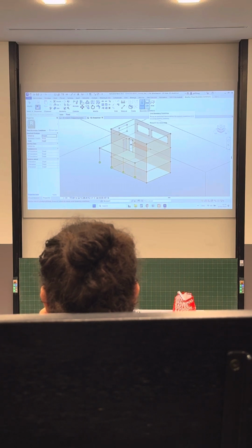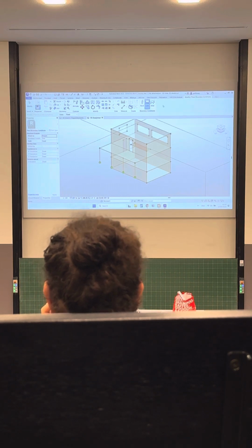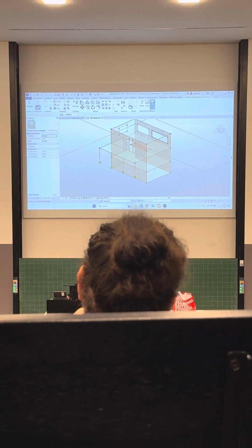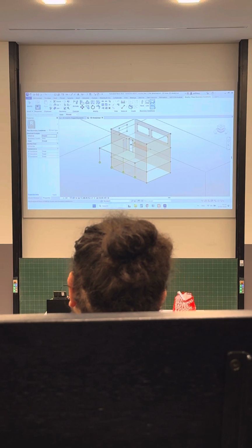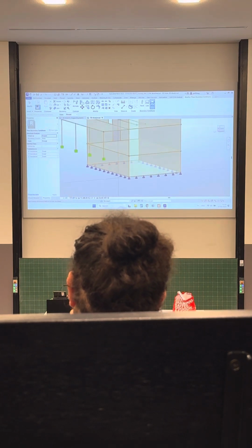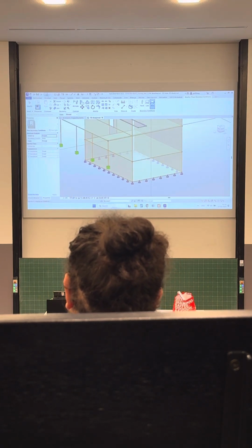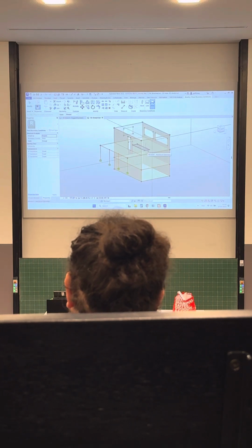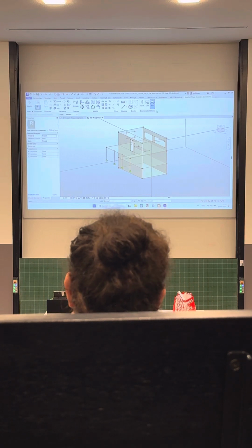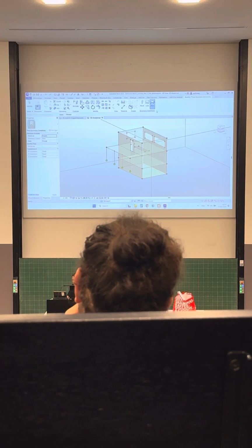And another thing, you also have lines and areas, and area boundary conditions. It depends, again, on your model, how it is going to be supported. I'm not going to use it here today, but for example, as I used previously in a project, I used an area boundary condition on the slab, to show that it's supported by the earth. But we're not going to do it today. Just keep it simple. But so you know that there are 3 different types of boundary conditions.